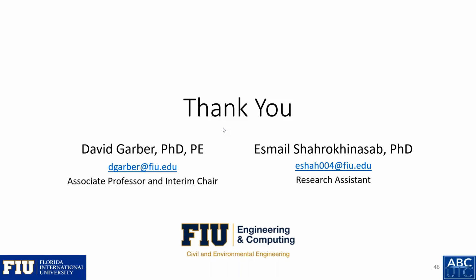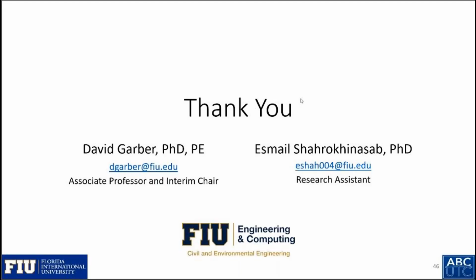Okay. We got a few fiber questions here. The first one, this came in new. Was there any fiber dispersion issue during casting for the hook-ended fiber case? Yes. We had to use, for larger fibers, viscosity modifying admixtures.